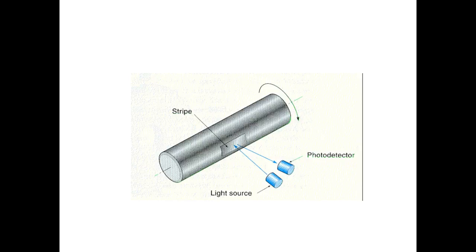So what we can do with a strobe tach is we pulse it, we change the frequency until the rotor looks like it's stationary. And if the rotor looks like it's stationary, it means that the light is doing what? Flashing at exactly the same speed as the motor's turning. If you see two things, it means you're going twice as fast. So we can use stroboscopes to measure speed. I think Nancy has a stroboscope on hers. What's real neat is you just point it at it, and then it gives you that reflection back. But this is one way that we can measure speed using a diffuse photoelectric, right? Everybody okay there?